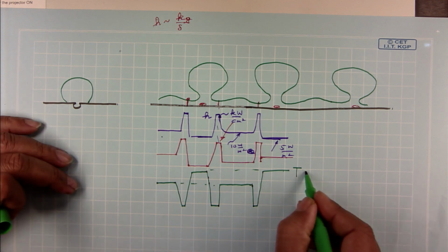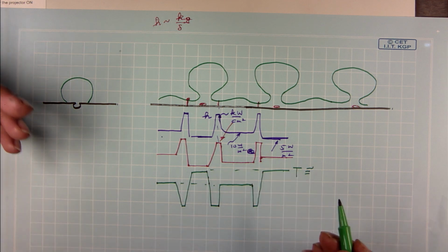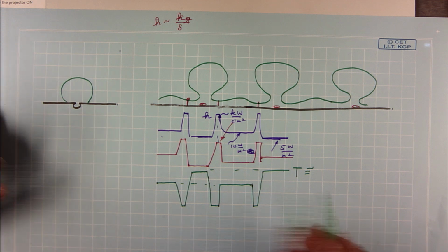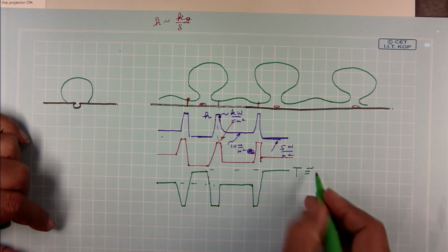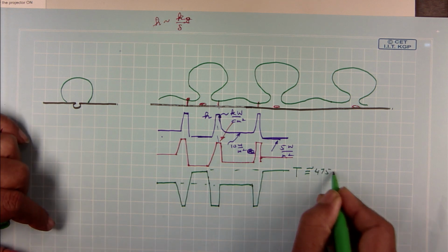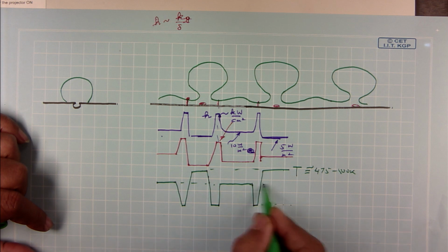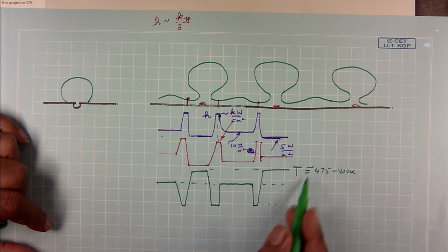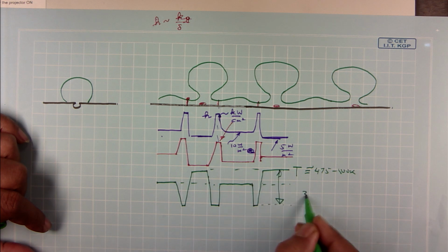This value of temperature will be something like, let us say if your boiling is at 373 Kelvin, for water you need about 100 degrees Celsius superheat to sustain film boiling. So, this temperature will be of the order of 475 to 500 Kelvin. Whereas, this temperature here will probably dip by a factor of about 30 Kelvin. This cold spot that is formed, a lower temperature region, so this temperature drop can be as high as 30 Kelvin.